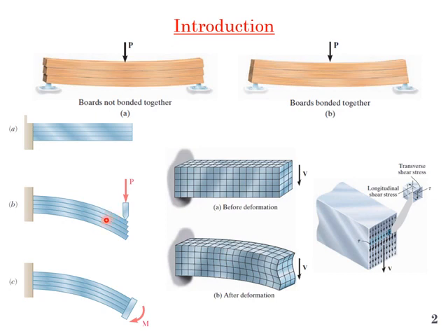This means there must be some shear force acting parallel to the surface of the planks, and that's causing the shear between them. Now, if we have a rigid plate and we apply bending moment, that will not be the case. In case of pure bending, this will not happen. This is only considered if we have multiple planks.